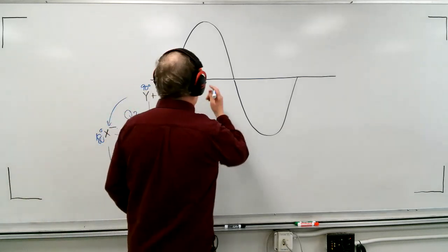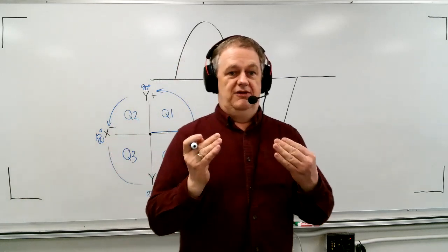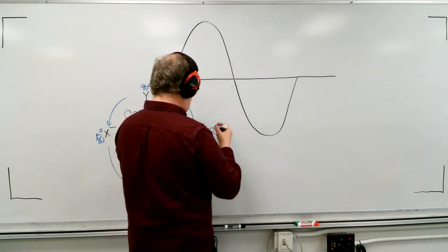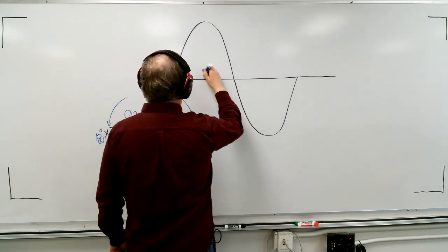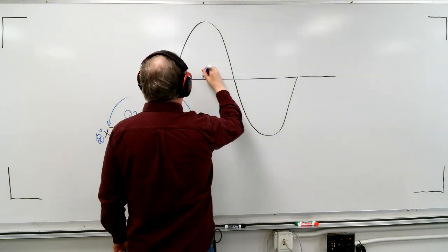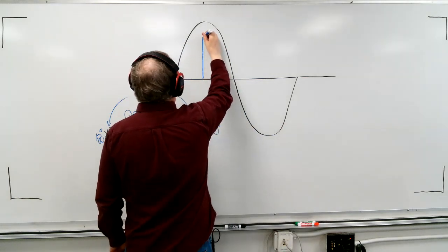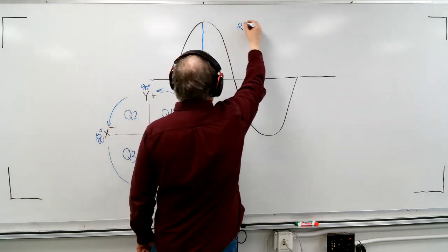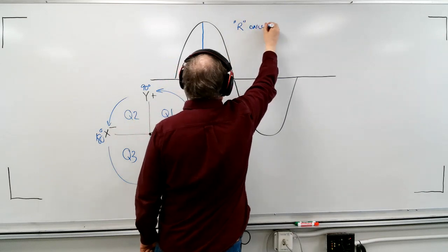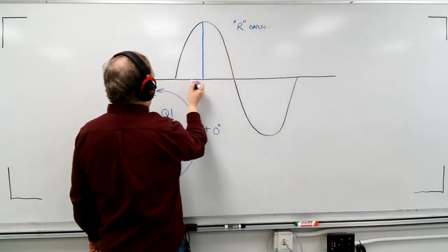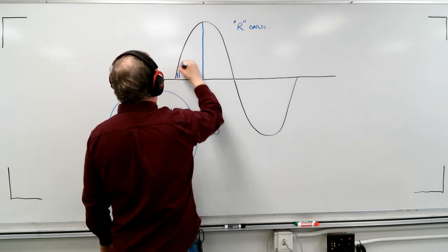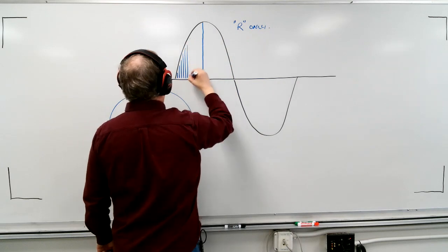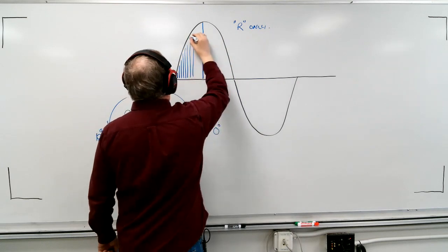What I want to show you is this. When it comes to the AC waveform, and we talk about control and the ability to control, we look at it in the same way. A triac used with resistive only triggering would only be able to actually control this quadrant, because with resistive only, we can only control up to 90 degrees.